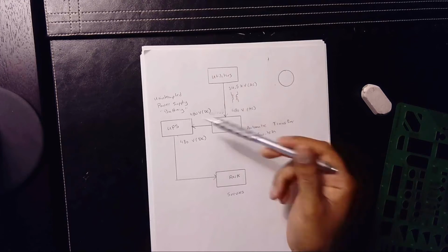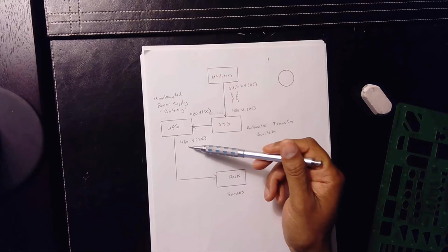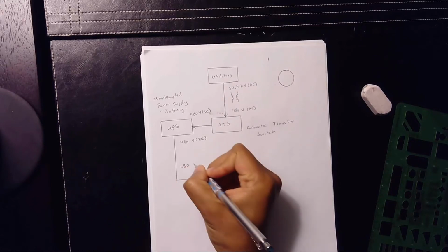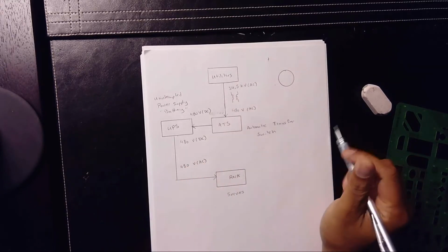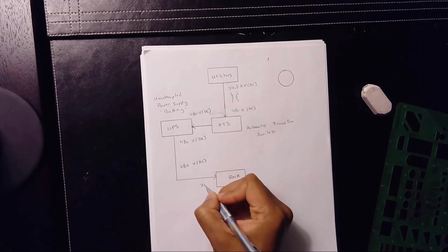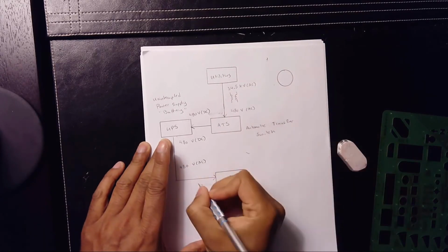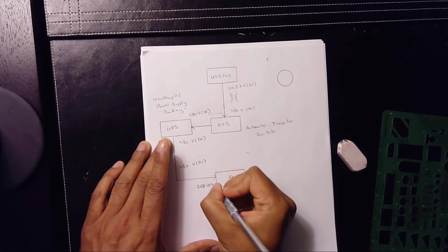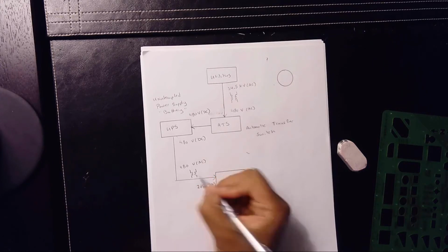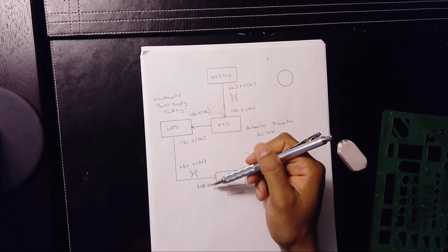So it goes from 480 AC to 480 volts DC. When the battery discharges, it goes to 480 volts AC. Then to the rack, it becomes 208 volts AC. And this right here is another transformer. So here you have an AC transformer drop, and you have the AC transformer drop here.